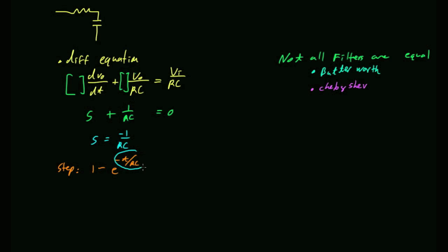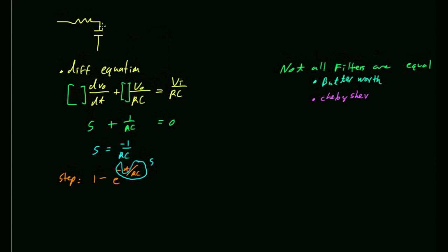Now, separately, let's say that we did the transfer function for this thing. When we did the transfer function, remember we said this was an impedance of R, this was an impedance of 1 over j omega C. And I introduced this concept that for j omega, we'll just use the shorthand. We'll call j omega equal to S, just to make it easier when we have multiple terms.